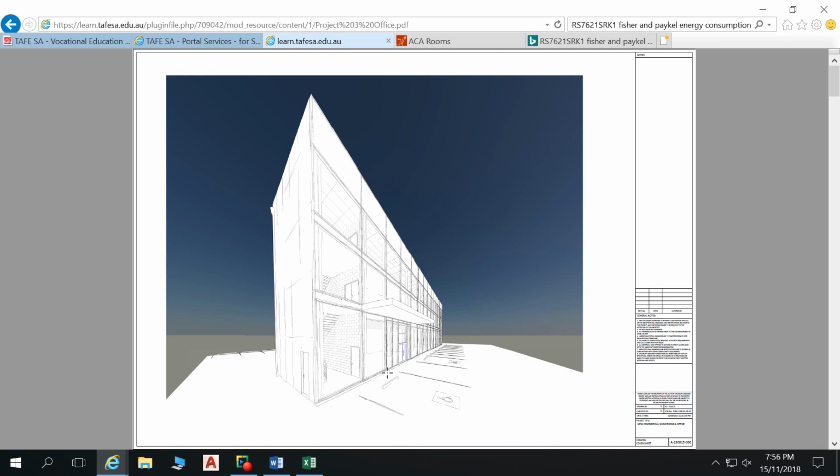And if you wish to make commentary on that and say, okay, we're set away from the boundary, that gives us flexibility in what we choose. We have car parks adjacent. If we were to have those car parks further away, that gives us greater flexibility in what we can use. Well, we don't have to have any FRLs then in that sense. It's just about fire separation between sole occupancy units.